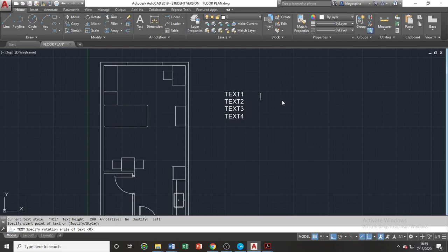Although single-line text can also be used for creating text with multiple lines, unlike the multi-line text command that creates multiple lines in a single selection, when multiple lines are created using the single-line text command, each line will be independent from each other, wherein each line will have a different selection. Here, I will demonstrate later on after we input our text. So let's input the same text that we entered using our MText.